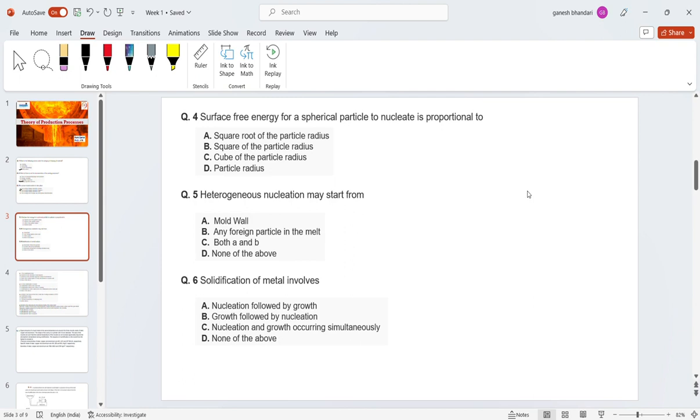When you see the SEM micrograph of lead-tin alloy, you will see lamellae, where in one region tin is enriched while in the other region lead is enriched. You can also study their eutectic behavior at around 180 or 190. 60% tin and 40% lead has the eutectic point. So there are different eutectic points also.